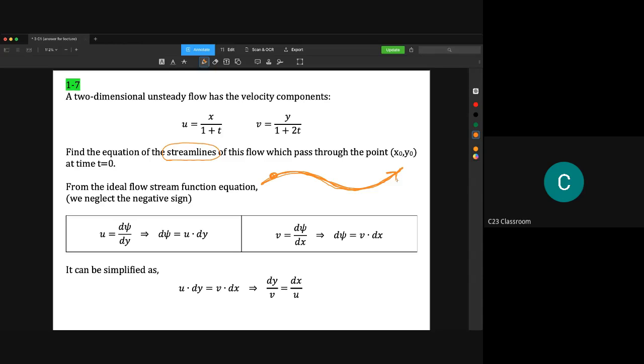Another idea to know what the streamline is: we get the value of velocity at each point. So how do we get the velocity at each point? First, you can use an experimental way, you could use an anemometer, or you can tap the pressure and then do a calculation, because for a streamline you could use the idea of the Bernoulli equation. We have P over rho g, V squared over 2g, and Z.